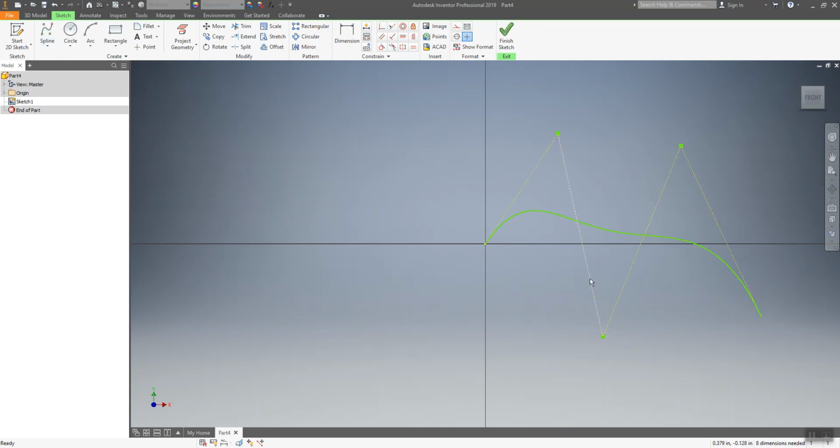And now you'll notice that I have some points up here that I can actually move around to change the curvature of this line. And I have 3 of those points, so they can be moved once they're established, and you can actually remove them if you need to, but you can move these around after you create your line to add more contour or flow to your line. And so there you go. That's a little bit about lines and splines.